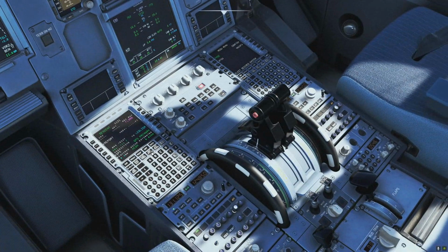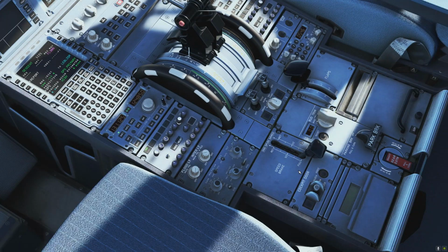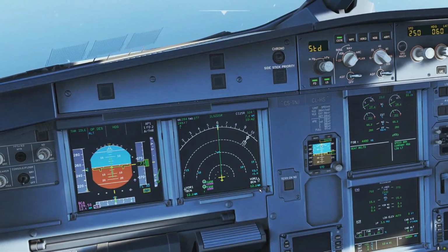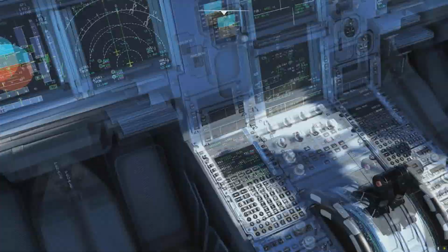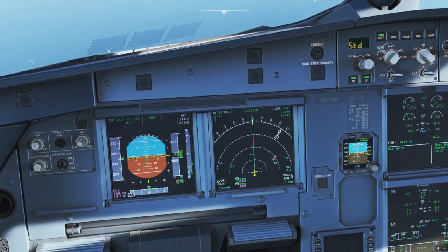So at this point I would use the speed brakes. So we deploy them. You can deploy them full if you want, but like I explained in another video, on the A320 series, as long as the autopilot is on, they will only deploy half deflection. So if you're really desperate, you could now switch off the autopilot, then you get the full speed brakes, and then maybe put the autopilot back on should you want to. For the time being, I'm quite happy with this.